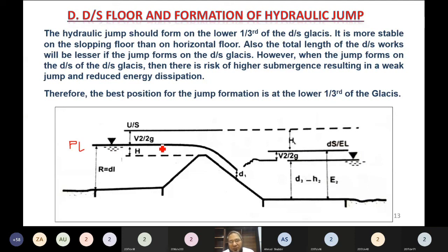By the way, how do we fix pond level? Pond level कैसे fix करना है? क्यों भी barrage का pond level? It should be where? We have to see that on what is the highest flood level, what is the flood level on this designed flood. Okay, let's say design flood पे ये level आता है, for design flood, and then we have to see that how much the water will rise due to provision of this weir and due to damming action. That rise of water level is called as, on upstream side, what it is called?